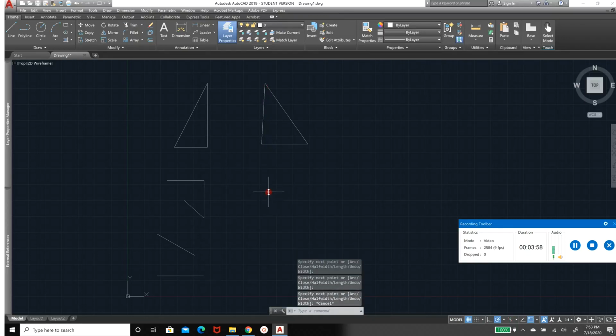And then I'm pressing the spacebar to do it again, and I'm just clicking. So the next line, this one I'll make it 5 inches, enter, and then I'm just clicking, and this I'll have it be open as well. And then remember, press the space bar, and then you can draw another line, enter, to be done. You can either click enter or escape once you're done drawing.